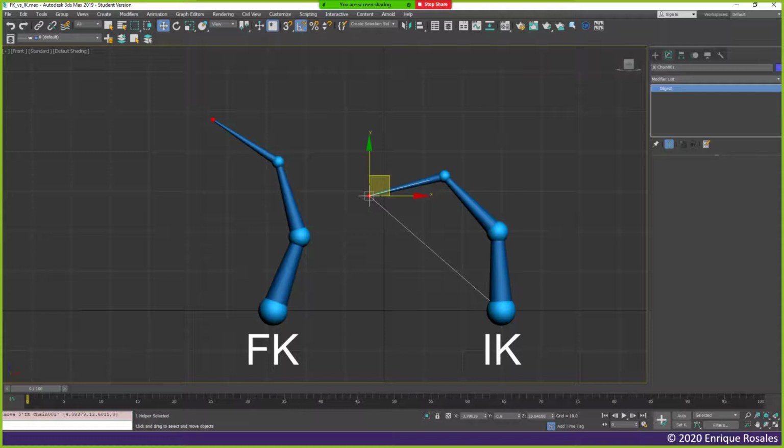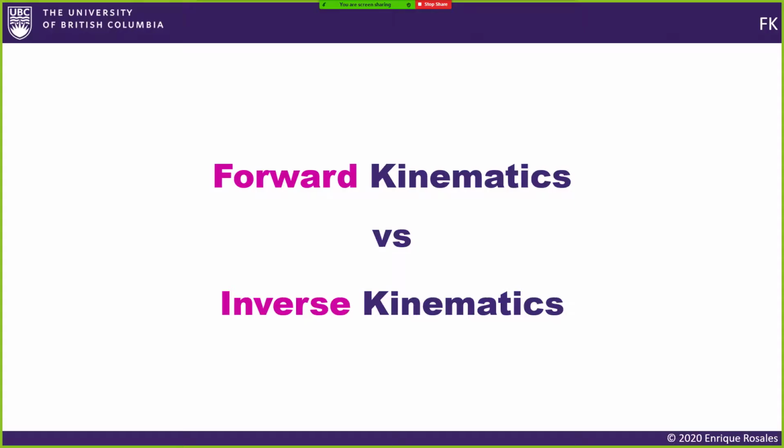What I mean is, if you want to make your robot dance, for example, you can just say, oh, I will rotate the arms of the robot by 30 degrees or whatever, but you don't care about the position of the hands at the end. You're just making the robot dance. It's just rotating. You don't care. But if you want to make the robot write, that is different. Because if you want to make the robot write or draw something, you are defining the end position of your hand. So that is inverse kinematics. That is the difference, conceptually speaking.